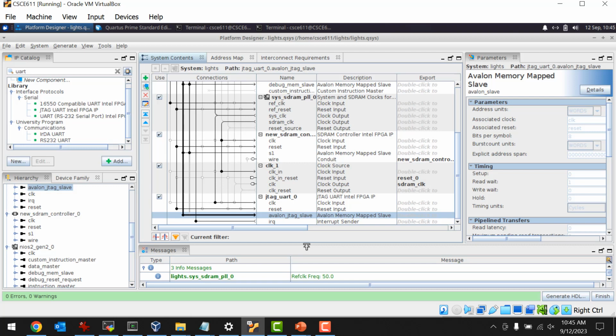such that when I put this on the FPGA and then open Signal Tap, you remember? You use Signal Tap in 313, 611. Signal Tap uses JTAG, and it allows me to create virtual logic analyzers in the FPGA. A logic analyzer, after a triggering event happens, captures data on every clock cycle and lets me see it and display it in a waveform. So I can look at signals in Signal Tap. You have to add probes and recompile your design, but once you do that, you can use the computer as a logic analyzer and look at what's going on in the FPGA.